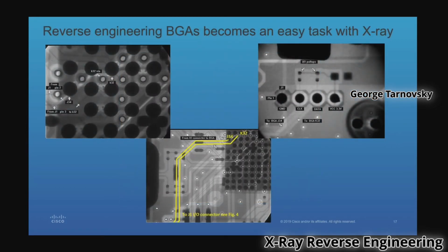Okay, so here's another BGA. Okay, so it becomes cumbersome to actually work with a BGA because not all of them connect. If you look at this particular illustration on the left, you notice that not all the BGA balls go to a via, any of these vias. So obviously, this one here makes contact to that, so you're able to touch that BGA ball. This one here goes directly out, so you wouldn't be able to even detect where it was going. So that's problematic. But in any event, we got through it and we found where it was, and that was a typical job.